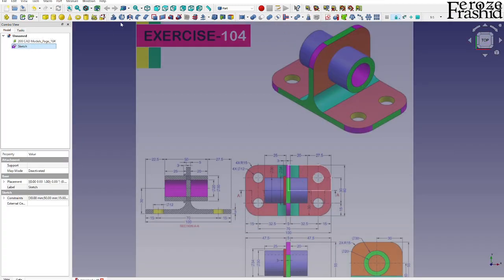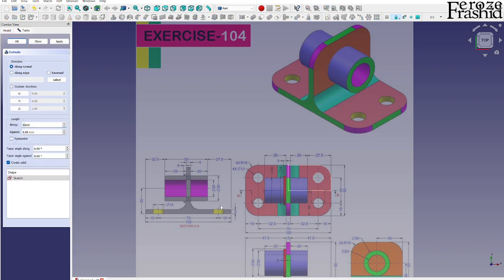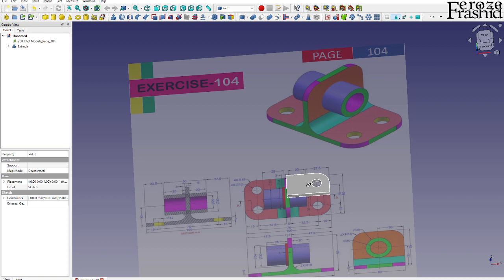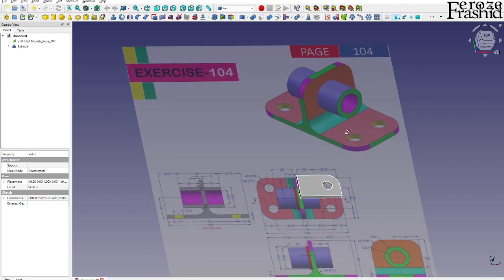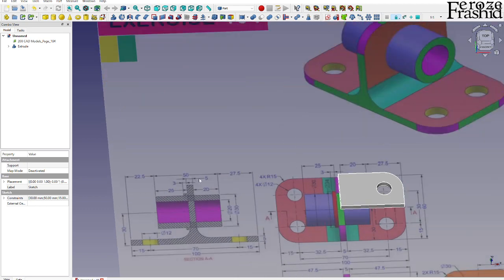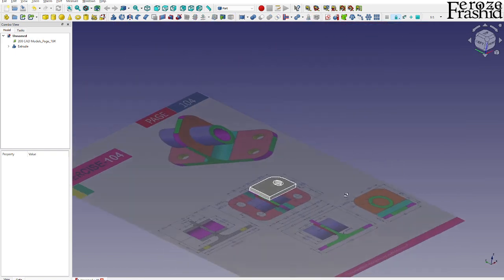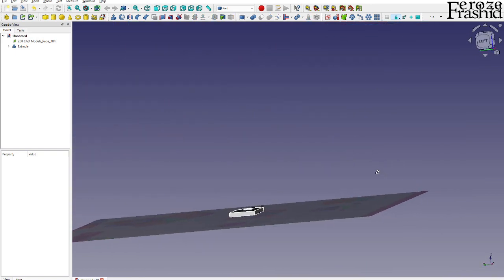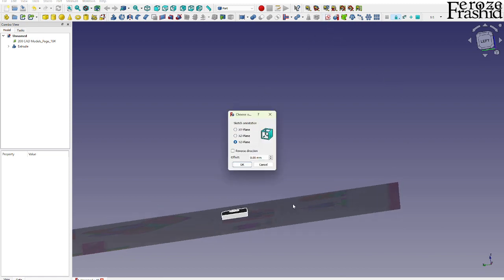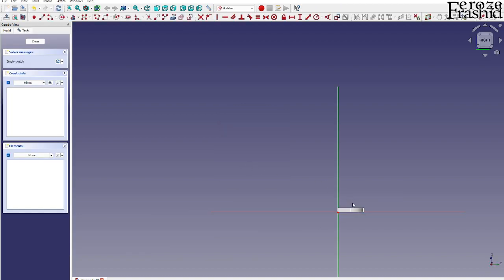I want to extrude that for 5 millimeter, and that's our first corner. I want to start working on this wall, which, because I'll be using the symmetry to mirror it, I will have to build only half thick. So the thickness is 5, I'll be building only 2.5 millimeter. I want to start on this face, which is YZ, so let's say YZ plane.